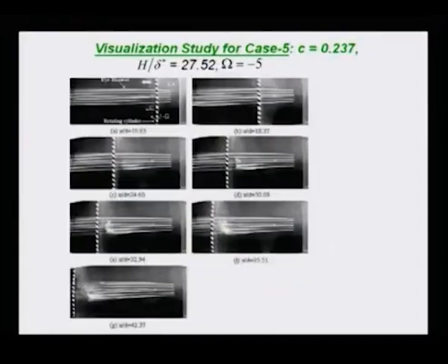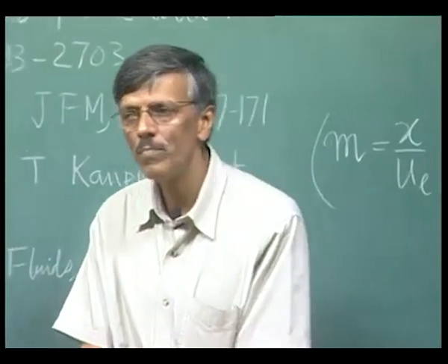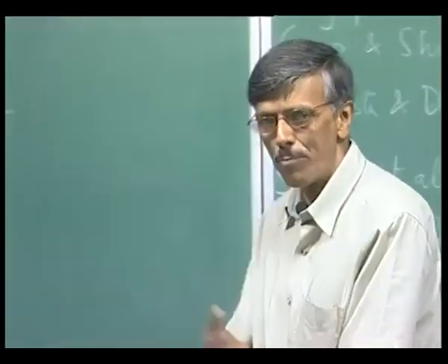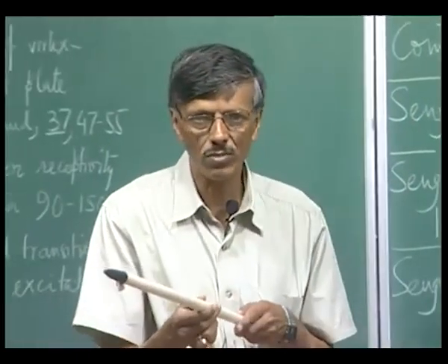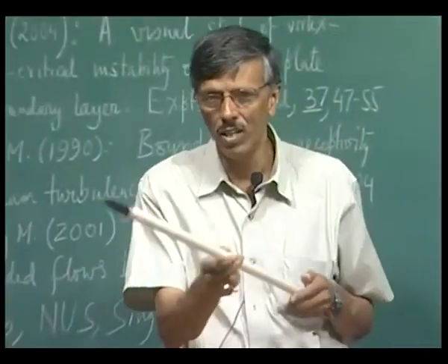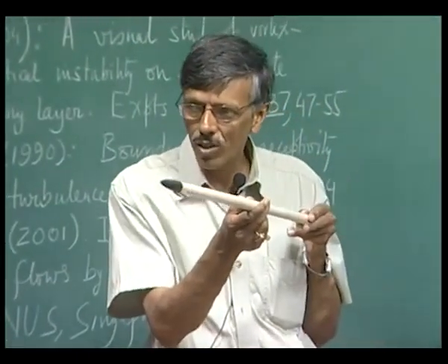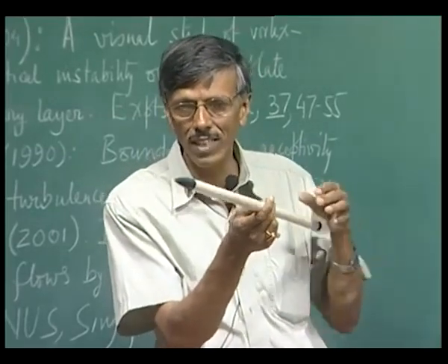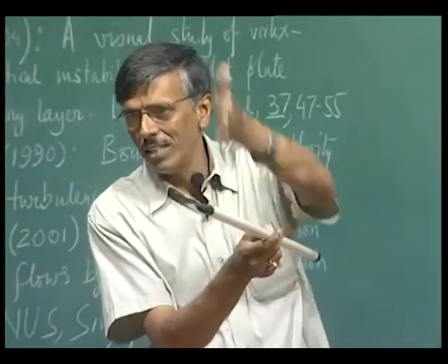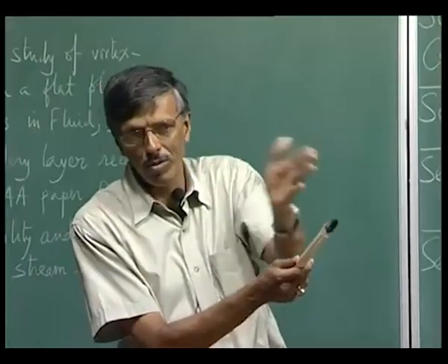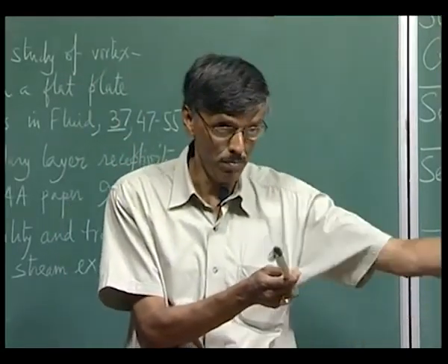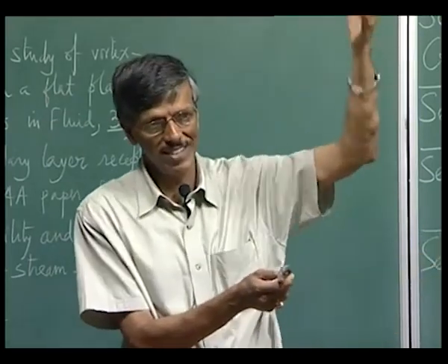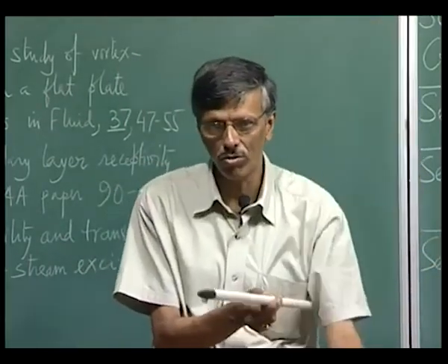So, what happens in this case is that the effect is occurring behind the vortex, and this is once again the same logic that we talked about. Think of the boundary layer like this, and let us say the vortex is going in the clockwise direction like this. If it does like this, then in the front it tries to reduce the thickness of the boundary layer, it imposes a downward velocity, whereas behind it, it has the other effect, it tries to scour it out.